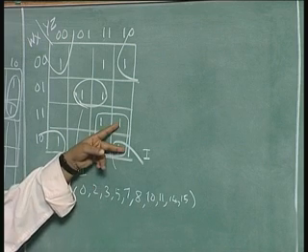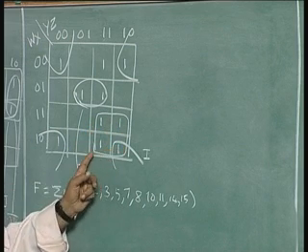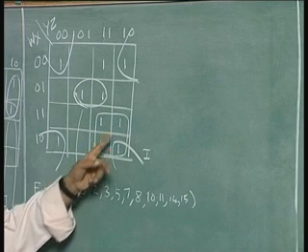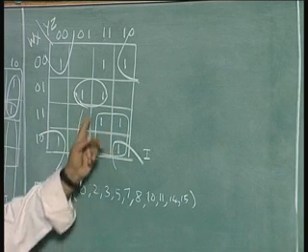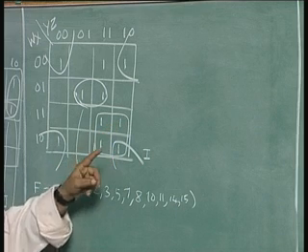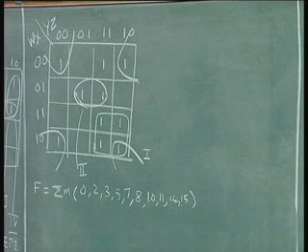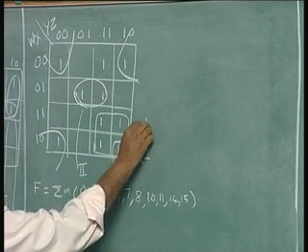So, this one is not a solution because when I have a larger prime implicant of 4, I cannot put this one as an implicant. So, I have to cover this. So, this is an essential prime implicant for the simple fact this one will not be covered otherwise. So, this will be number 3.